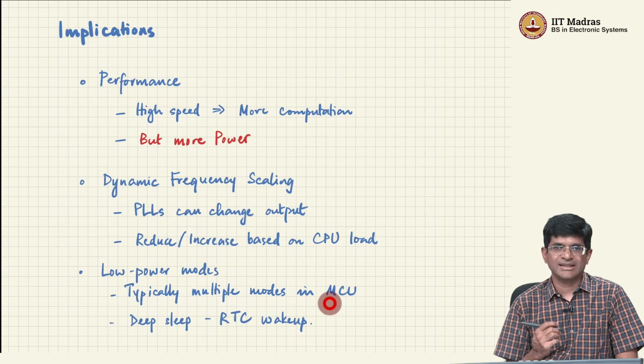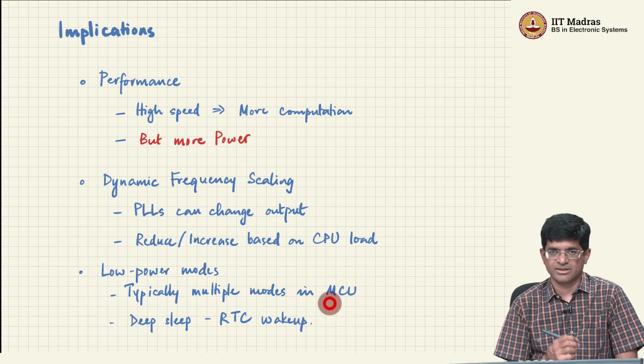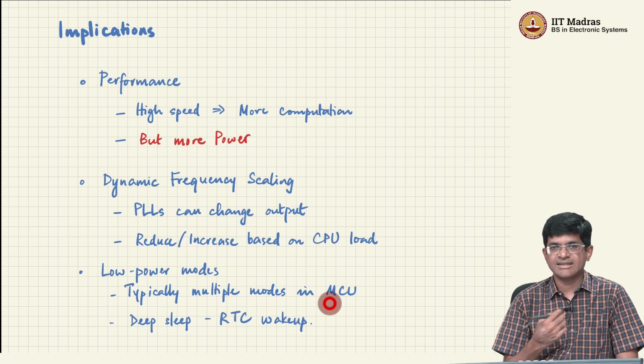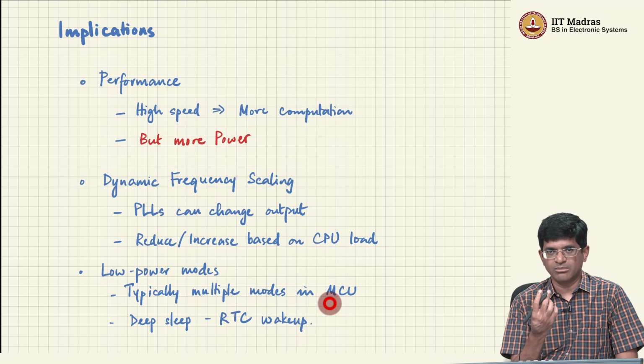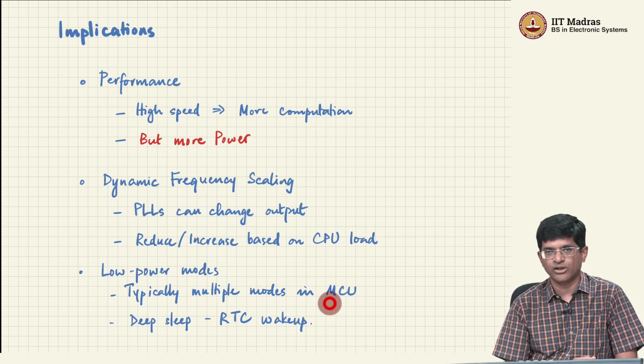What that means though is that there is still something that is providing power to that clock, right, providing a voltage supply. It draws a very minimal amount of current so that it can probably last even for months, possibly even for years on that real-time clock, and then suddenly wake up and do something useful. Right? So those of you who have seen things where there's one button cell that powers systems for like ages and ages, this is the kind of behavior that it has.